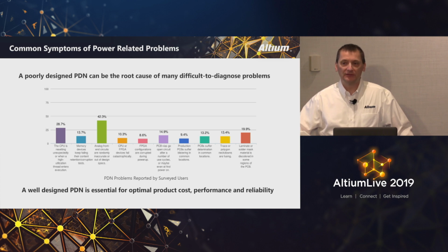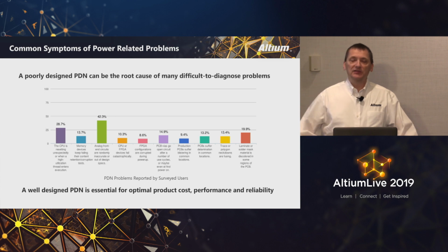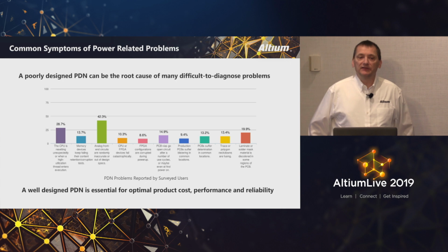They would create a big enough ground bounce to kill the power supply. The analog power that was feeding those switches exceeded the current capability of the supply, and actually over-voltaged it in a way that it didn't like. So it's a perfect example of a worst case scenario.